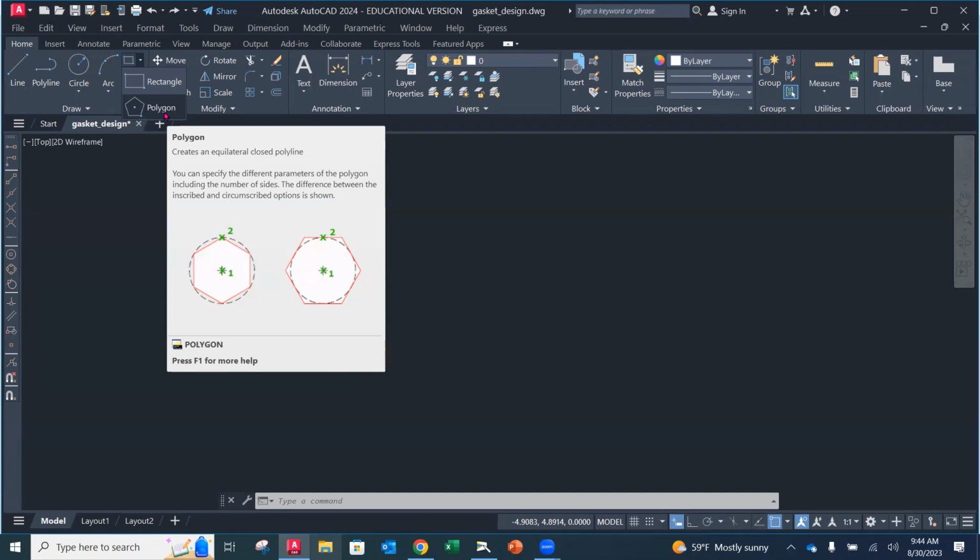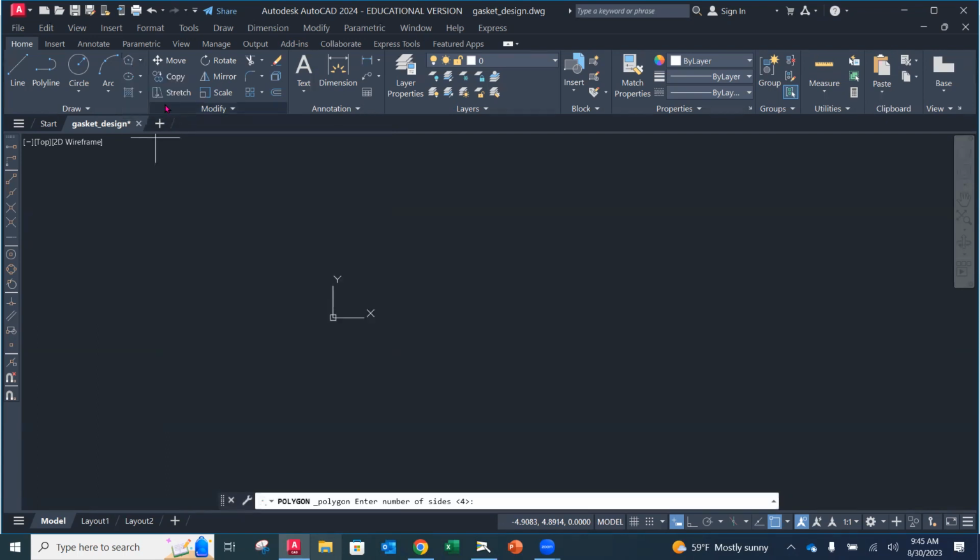If we just create a regular square with lines around the outside, we'd have to strategically place where we're starting and ending our lines if we wanted it to be about a center. But when we have a polygon, it has a geometric center that we can click, just like a circle. So we're going to click polygon.